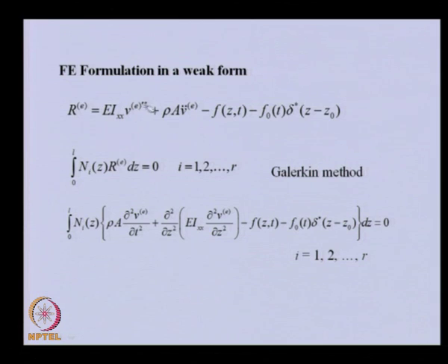This governing equation which we derived earlier was valid for each and every point on the beam. So, obviously, it will be valid for a particular element also. That is why we have substituted the solution of the element into this. So, we got some residual, and using the Galerkin method, by multiplying by some weight, and in this particular case this weight will be the shape function of the problem itself.